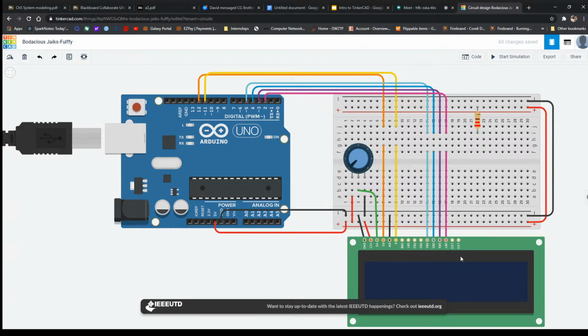And then for our last two, our LED anode and cathode, we're going to be connecting the anode to power, but this time, instead of directly connecting it to the power bus, we're going to be connecting it to the resistor, which is over here. Remember the 220 ohm resistor that we set? Let's change this to brown. And then the cathode, we're going to be grounding that. So that'll be black.